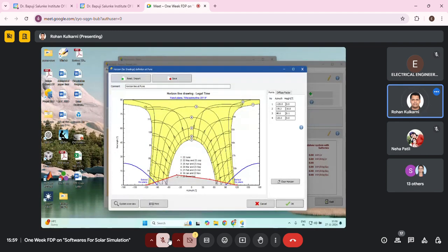Normally, in the calculations, we keep the panels in open space because we don't want any shadow on them. That is the reason. But even if you want to calculate, if in the morning at 6 o'clock you have some shadows, it doesn't matter. In the evening after 6 you are getting some shadows, it's okay, because after 6 you don't have much sunlight available. But if you are getting shadows in the time span in between, like if I keep one shadow like this, then it's a problem for you. So those parameters we need to check or calculate.